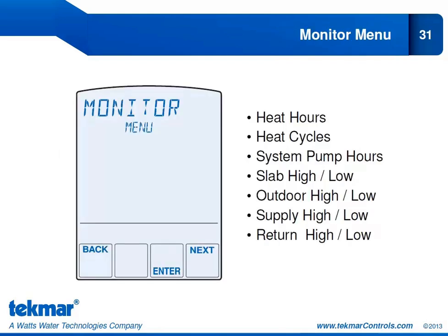The monitor menu contains a lot of useful information for you to determine how your system has been performing. It will tell you the amount of hours that heat relay has been closed and the number of heat cycles that it has seen. You can look at how many hours your system pump has been running. And then you can look at some trends. What was your highest slab temp and what was your lowest slab temp? Likewise for outdoor temperature, supply temperature, and return temperature. So this can be very useful for you to determine if your system is performing the way you expect it to or the way you want it to.